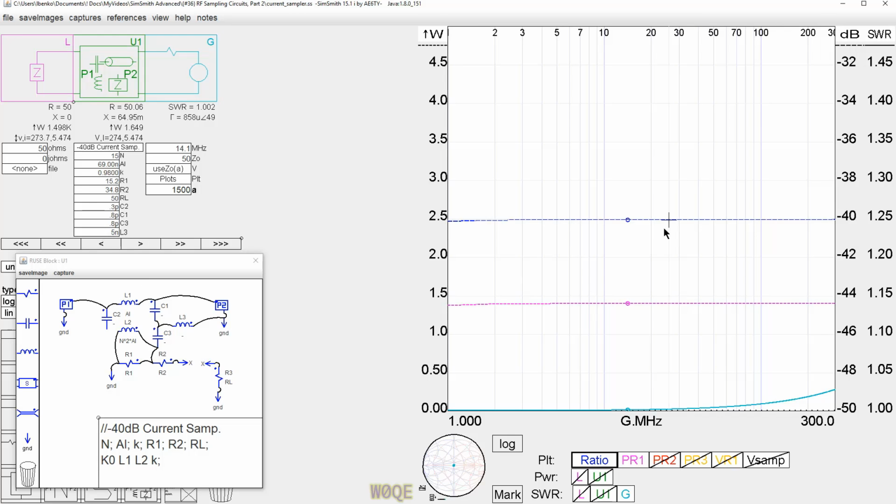And what we can see is all of a sudden we no longer have the change in coupling factor here. And as we make the ground get further and further away from the toroid, so that this path becomes higher impedance, we see it doesn't change much. So we have a pretty good way of negating this capacitance in this core. Now the circuit I'm going to show you did not do that.